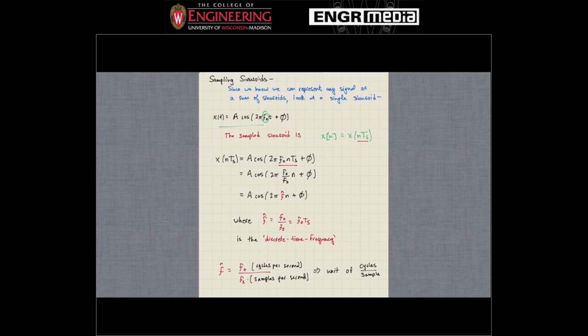All right, and T_s equals 1 over f_s, where f_s is the sampling frequency. So I can just write that as the ratio between the frequency of the sinusoid, f naught, and the sampling frequency, what's circled right there. We're actually going to define that to be the discrete time frequency. So the ratio of the frequency of the sinusoid to the sampling frequency is going to be defined as f hat, and that's referred to as the discrete time frequency. That's all written right here. We'll see exactly why we do this in maybe not this lecture, but the following lecture.